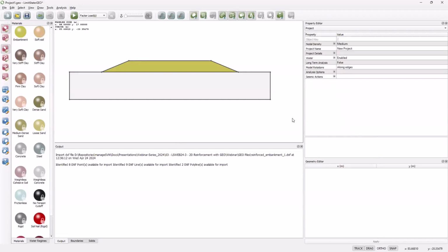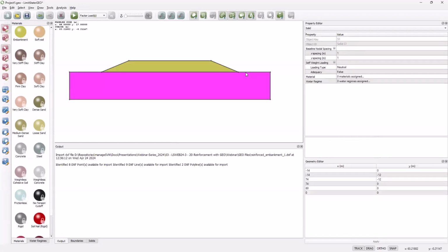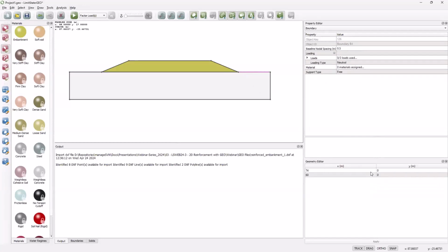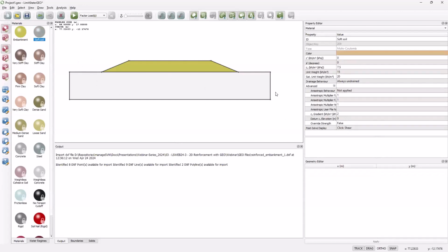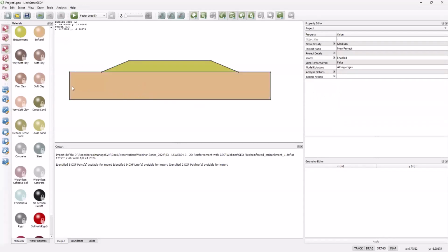So I just need to check on the problem where that is. So if I click at this level, which is where I want it to be, I can see that that corresponds to a y-coordinate of 0. So we've got that set correctly for our datum. So that's okay, and I can drag that over there and drop it in.